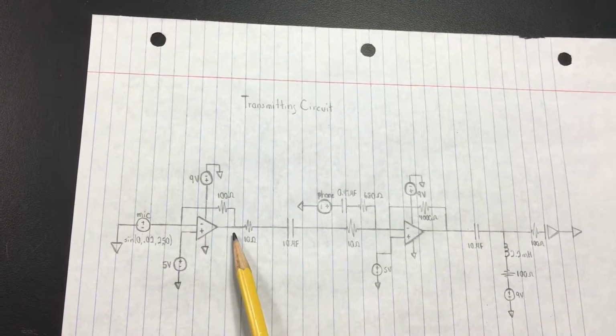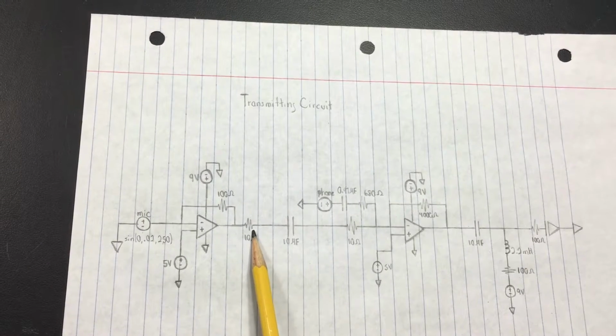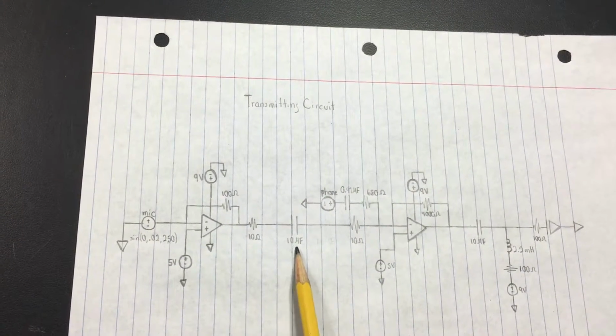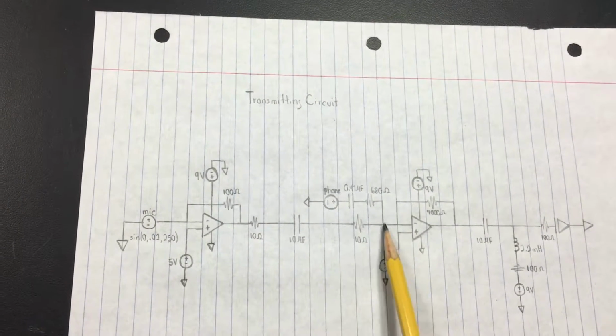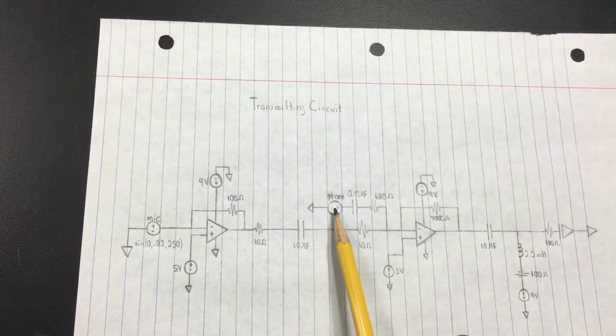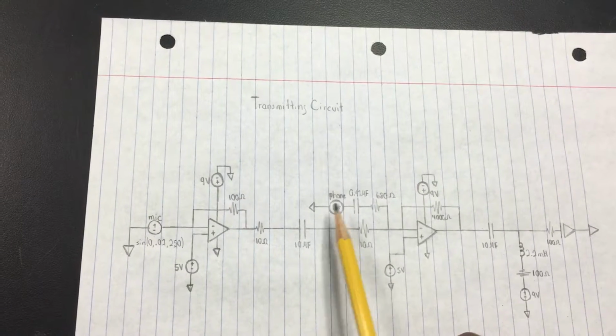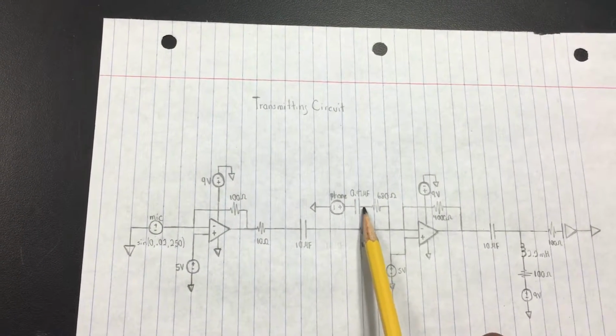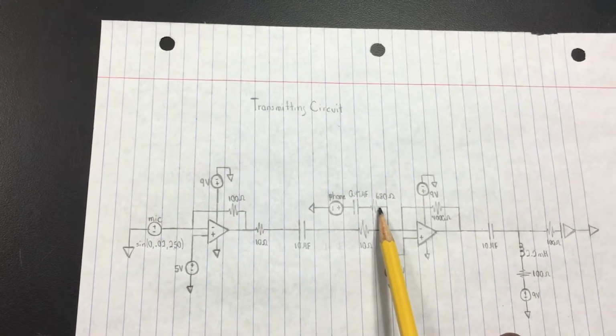And that amplified output is sent through this 10 ohm and this second 10 ohm resistor, which also goes through this 10 microfarad capacitor. And now the phone is connected via an auxiliary cable, and one end is grounded as the other end is connected to a 0.47 microfarad capacitor and a 680 ohm resistor.